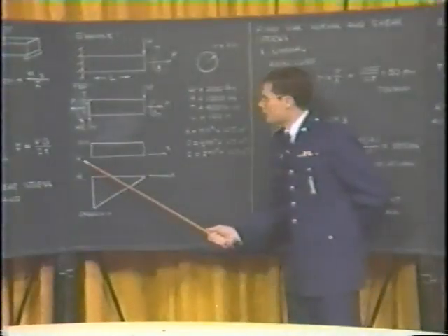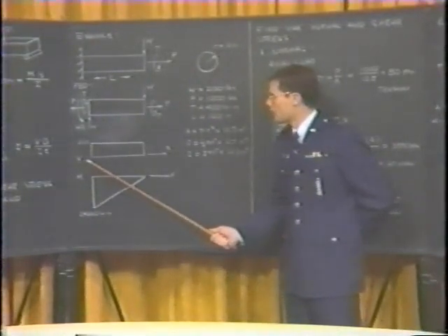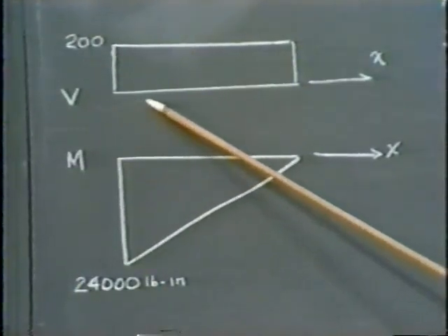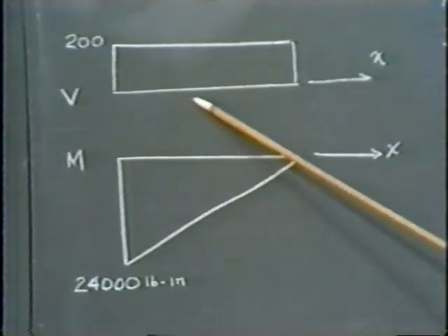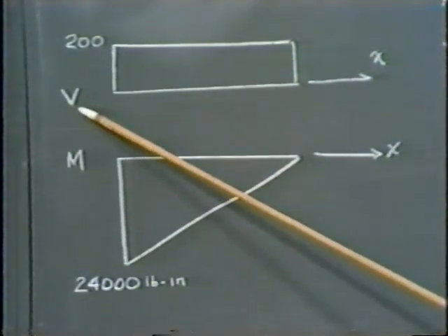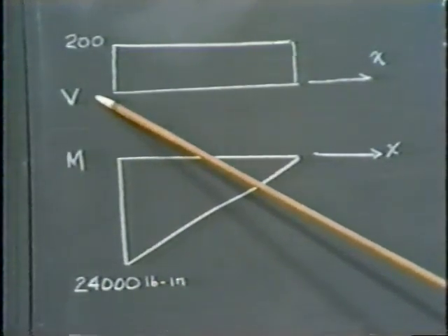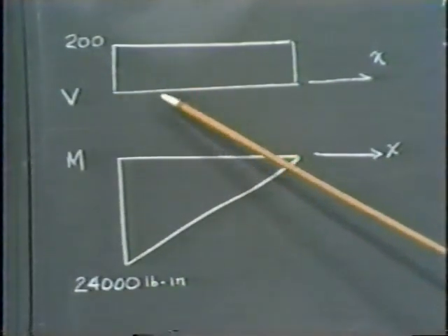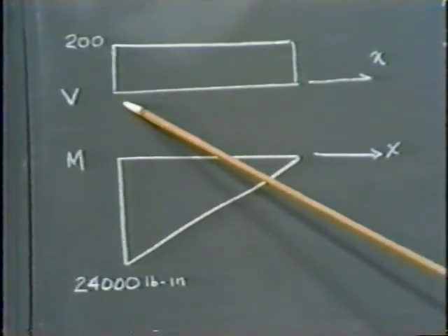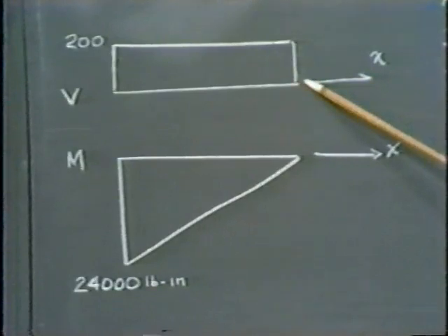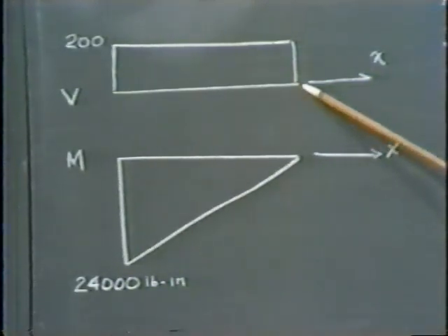We should be able to produce a shear diagram very quickly. Remember, plot on the vertical axis a representation for the shear force V. A horizontal axis should represent the length of the beam, call it an axis X, and we simply plot the external loads as though they were the shear loads. So we go upwards to a value of 200, the value of the weight W. There is no change in the distributed load throughout the length, so we close with a last vertical load downwards, also equal to 200. We've closed at 0, so we're assured that we've done this correctly.